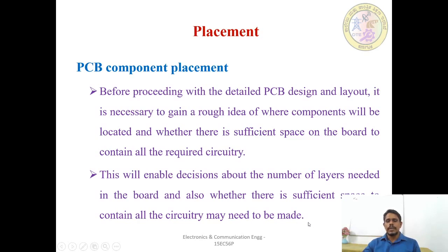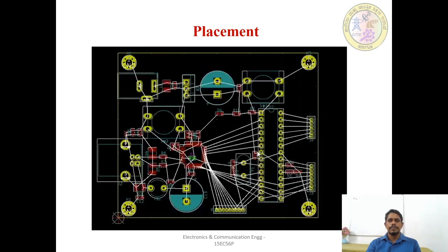If the PCB consists of more layers, the wires should be placed near the FPGA or the Spartan IC or the BGA contained in the PCB. Therefore, sufficient space has to be provided around it to place the decoupling capacitors as well as termination resistors and also for placing the wires.